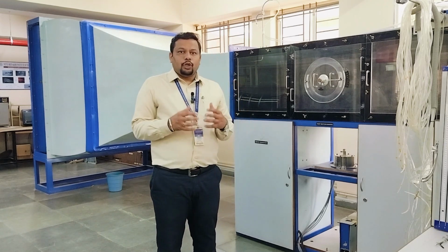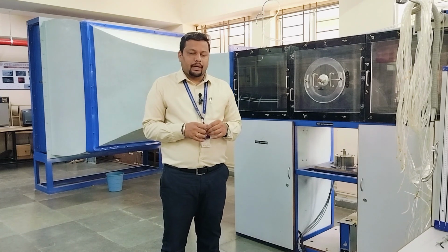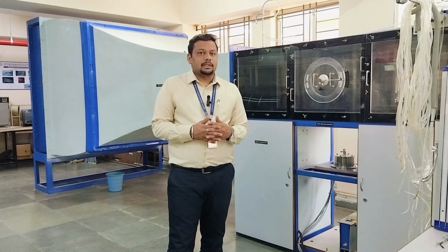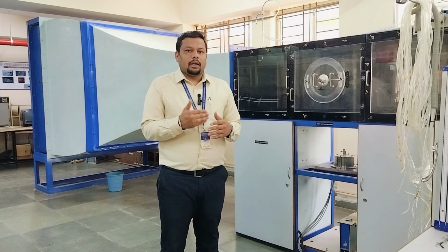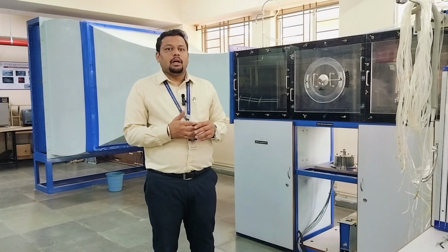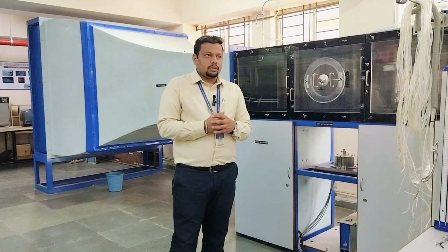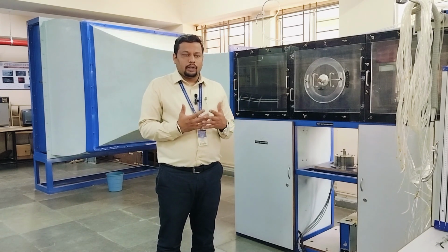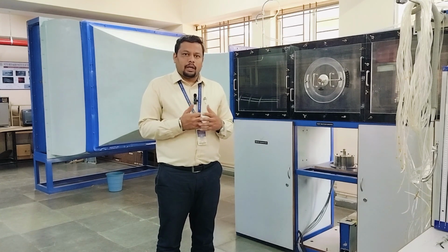In the Pitot tube, we will be able to measure the total pressure, and the static probe will be helpful in measuring the static pressure of the flow. With this difference, we can calculate the dynamic pressure of the flow, and from that, the velocity can be calculated. Now we'll discuss how the Pitot-static probe works and how Bernoulli's principle can be applied to get the velocity from the Pitot-static probe.